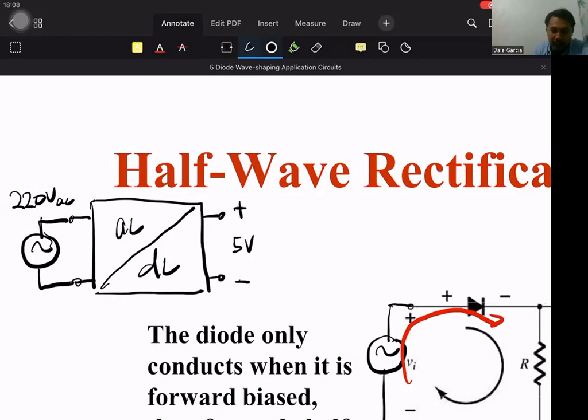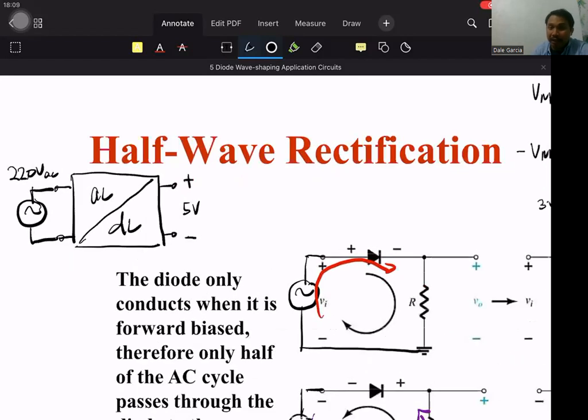So actually, only the head of the charger is the power supply. The wire, technically, is not necessarily part of the power supply, that USB cord or Type C cord. So only the head of our charger is the AC to DC converter. And again, the first step in the process of converting from 220 to 5 volts is rectification.